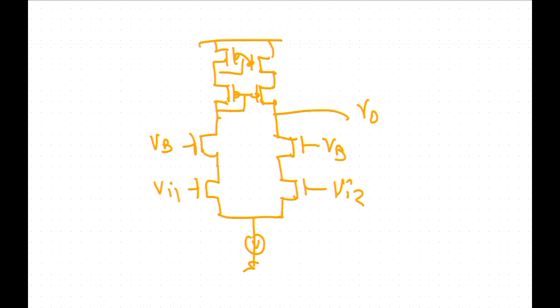So that means that if the input voltage goes up, you have to restrict what the output voltage is doing. And sometimes that is fine if you're making an amplifier in one of these super cascodes, where you have a very restricted voltage swing at the output and you know exactly what the DC value is going to be. That's fine. And this is good because you don't have these extra current mirrors that make this faster. It also makes it lower power because we don't have these extra branches where current flows. But the output voltage range is crap.